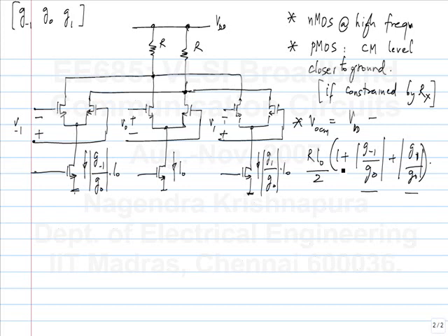While discussing crosstalk, we said that if you put the equalizer at the transmitter, of course, it won't amplify the crosstalk or the noise. But the problem is, if you have to realize a complicated equalizer, you can only transmit a small signal. So although you are not amplifying noise, you start off with a smaller signal. So the signal to noise ratio is still degraded in effect because of practical constraints.